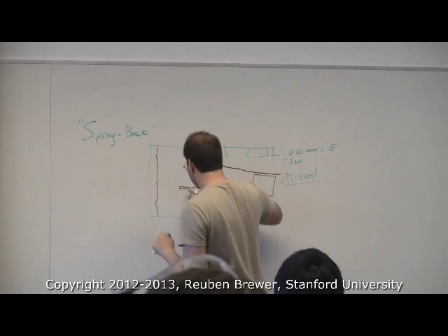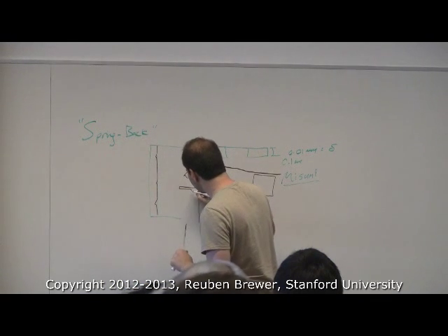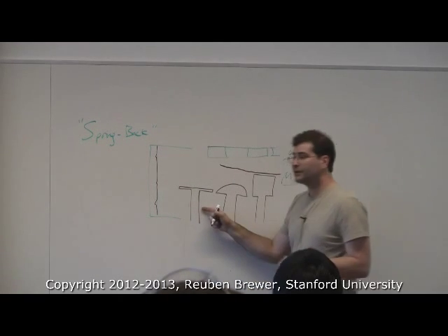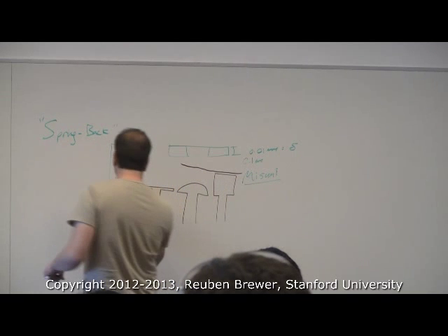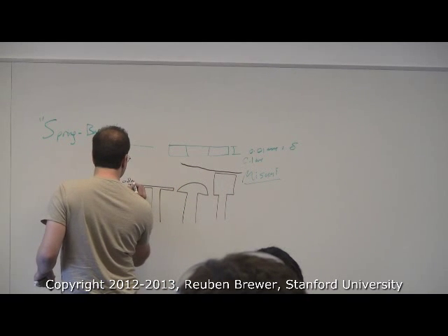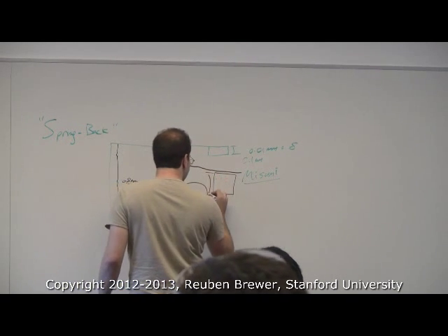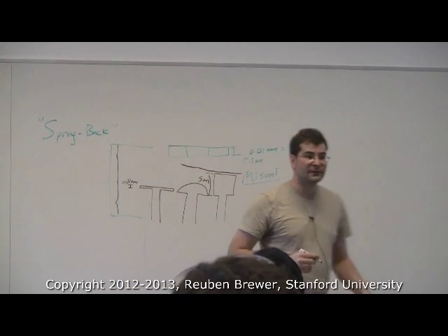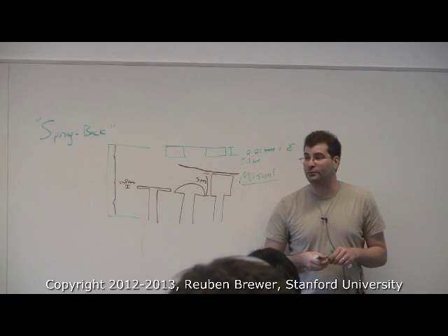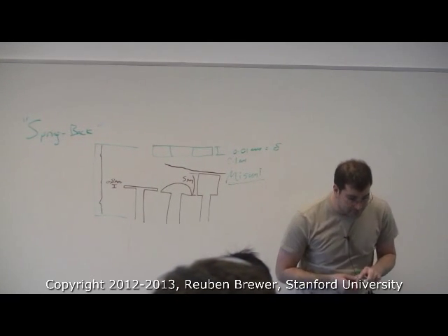I use these ultra low head screws constantly when I don't have space. So clearly you can see that these ones go down to 0.8 millimeters thickness, and this, at least for some of the M4s, is all the way up to 5 millimeters. So your 4.2 millimeter difference is potentially a huge difference.